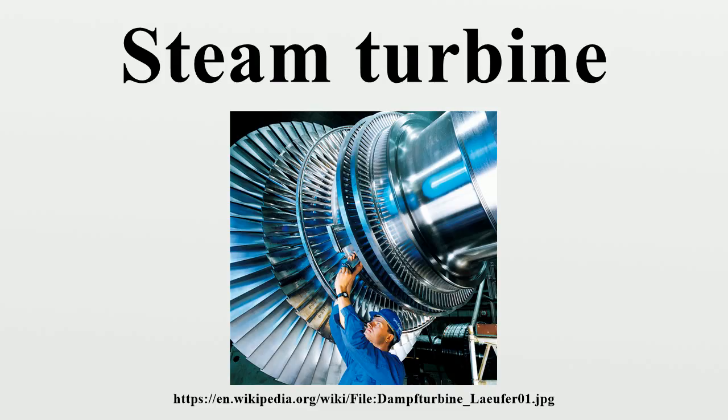About 90% of all electricity generation in the United States is by use of steam turbines. The steam turbine is a form of heat engine that derives much of its improvement in thermodynamic efficiency from the use of multiple stages in the expansion of the steam, which results in a closer approach to the ideal reversible expansion process.